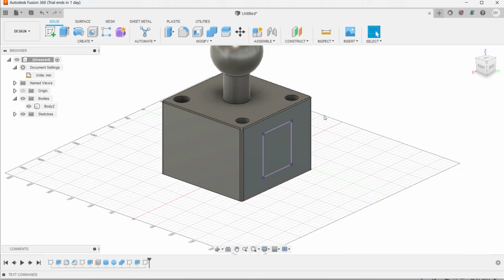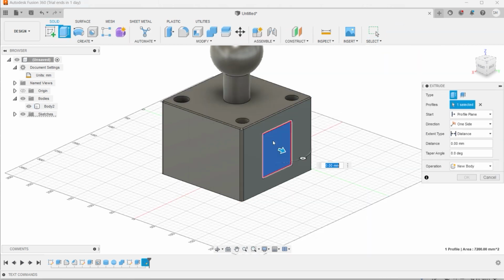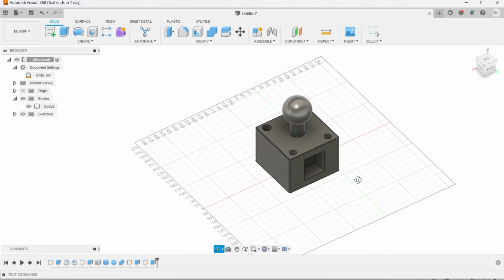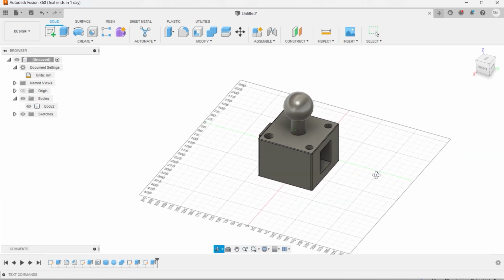Finish the sketch and select that space, and we can extrude this one, or you can remove material also as per our requirement. Suppose we are removing material with a depth of 50 millimeter, and the operation is cut. If we are removing material, operation will be cut. Okay, done, right? This is the option. You can use the projection to reduce the time for drawing.